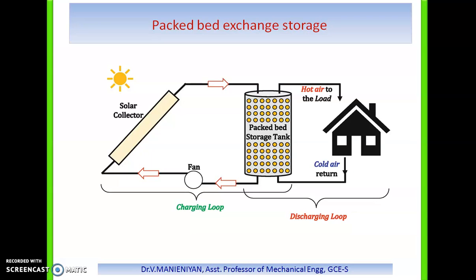Its thermal capacity is only about half that of water, and the bin volume will be about three times the volume of a water tank for the same temperature rise and the same time interval. So water is superior because of the lower material cost and lower volume required per unit of energy stored. However, rock does have some advantages over a water storage system.